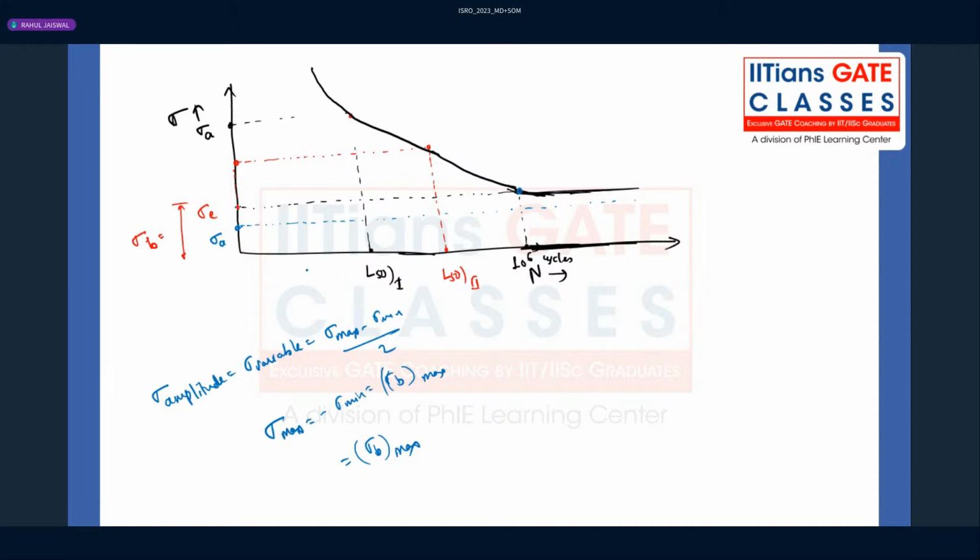And how do we define endurance limit? We say that if we are putting the shaft for transmission purpose, the cost has to be justified. When will the cost be justified? When it completes at least 1 million revolutions. There we define the endurance limit or endurance strength of a component. Just like we define yield stress in a UTM testing machine, similarly, this test has been conducted to determine endurance strength. But put a note and note down.